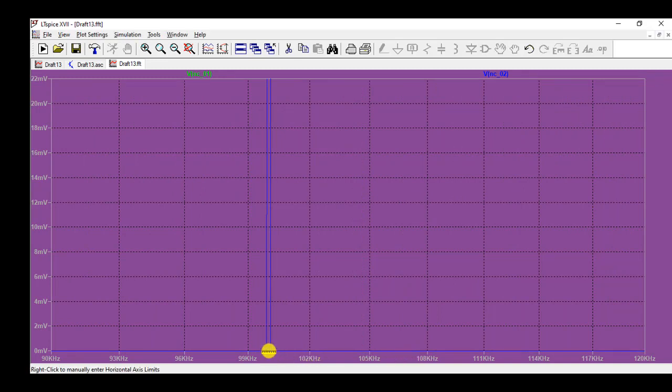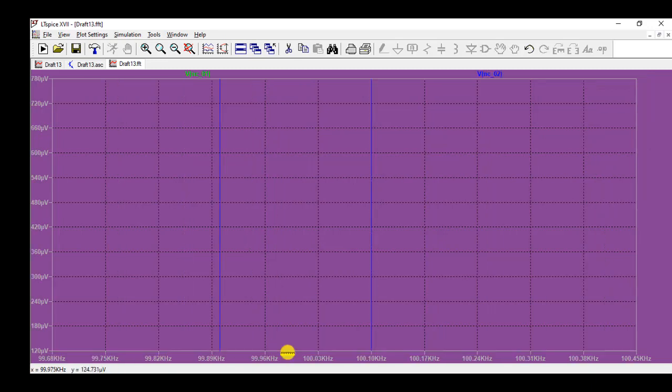We do. We can see that the carrier signal was peaked at 100K, but we can see a range of frequencies around 100K. Therefore, we verify that indeed modulation introduces sidebands and generates an array of different frequencies.